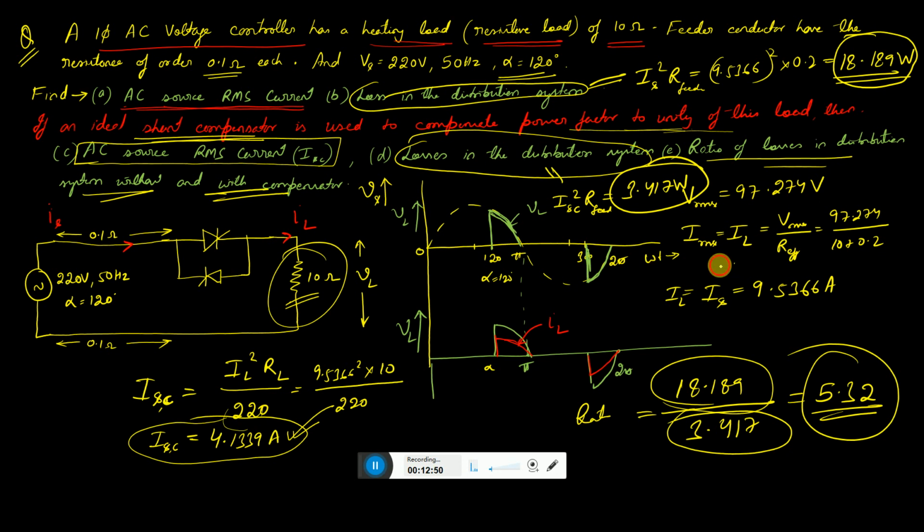Before compensation the current is 9.5366 ampere, but after compensation it is 4.1339 ampere, and what we save is the losses in the feeder, which are reduced by 5 times. So this is what we learned in this video.